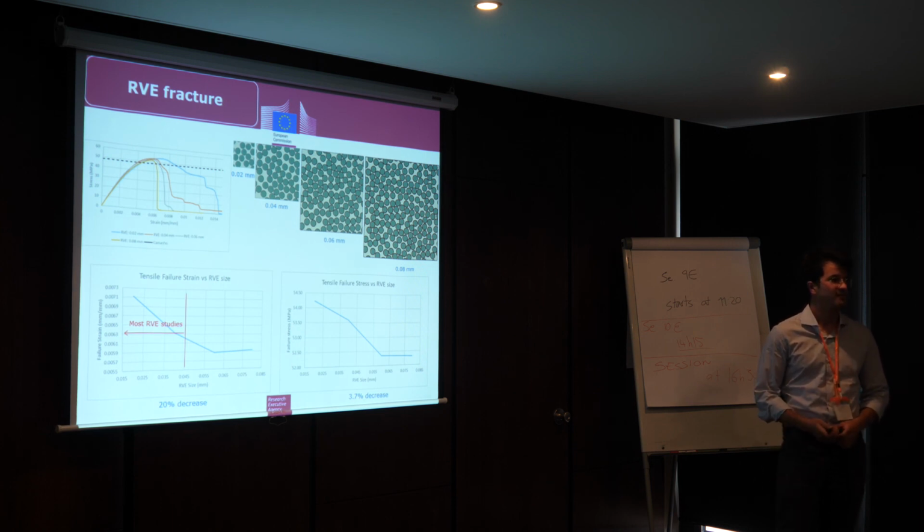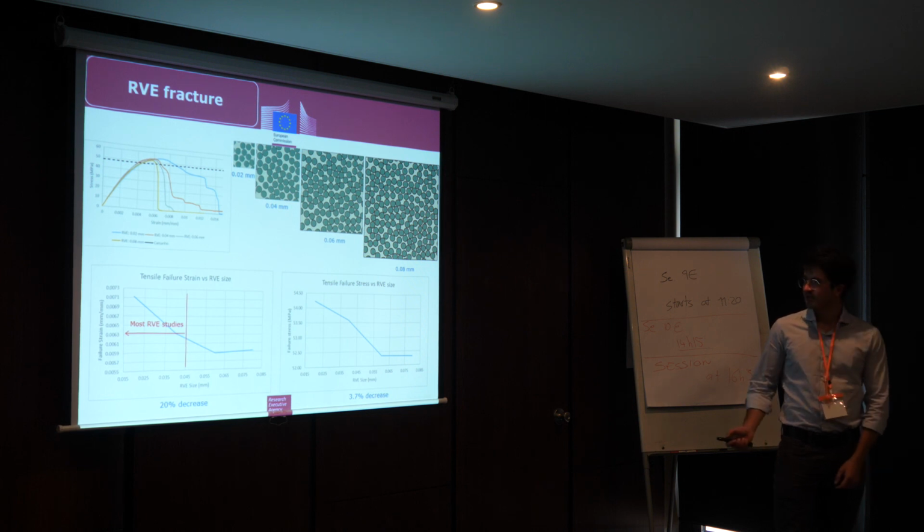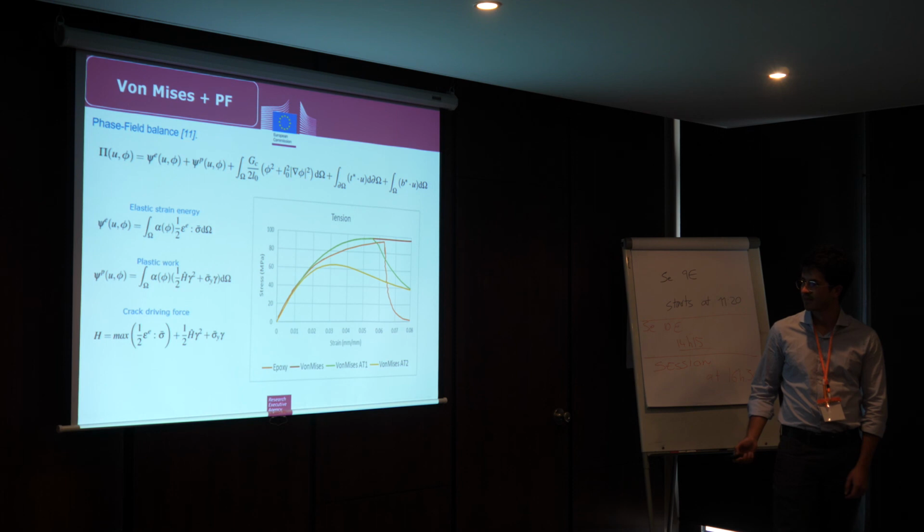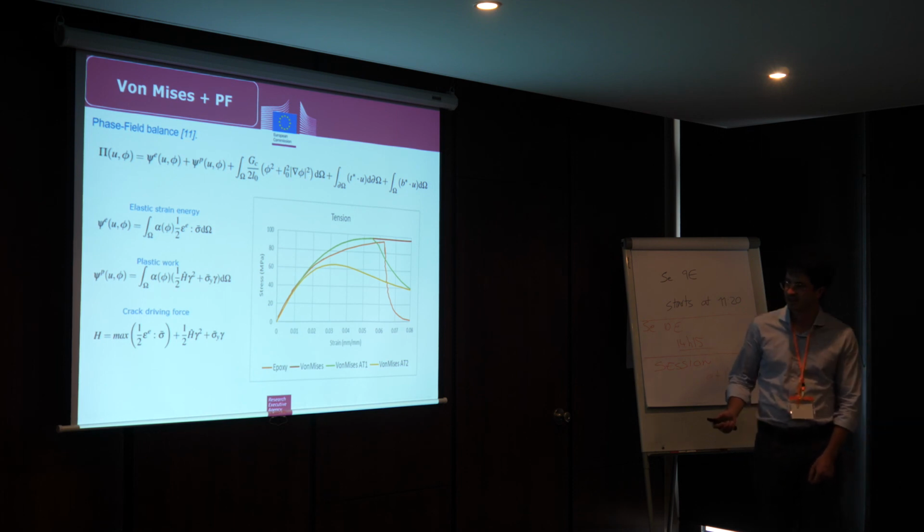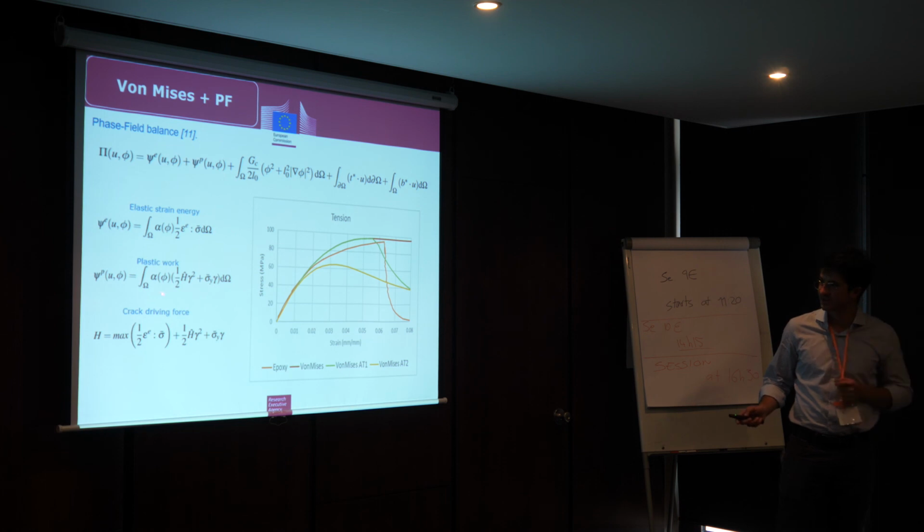Yes, please. Just one curiosity, you apply the split only to the elastic part, and then I wonder if you tried having as driving force only the elastic part. It seems that you combine both as driving force, right? Elastic part. Yeah. I wonder if you tried only elastic, if you saw any difference, because you have the plasticity in the bulk and so on. Yes, so depending on the formulation, that's one of the approaches, actually. I think it is Lorenz's approach. So she doesn't have this coupling, so the degradation function does not affect the plastic part, and then the driving force is just the elastic part.